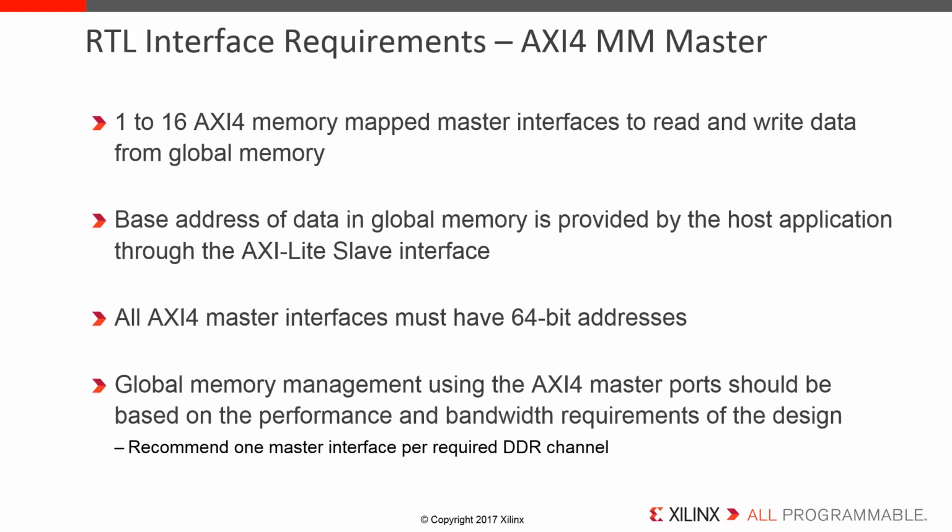Note that AXI masters must not use wrap or fixed burst types and must not use narrow sub-size bursts, meaning that the size should match the width of the AXI data buses.